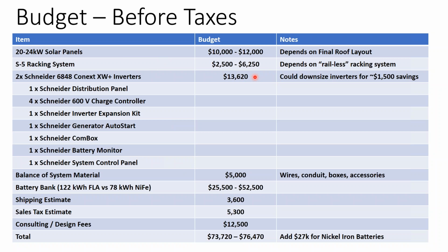In fact, it was more like 60 cents per watt. Now, normally a high-end inverter budget at the residential level wouldn't be more than 30 cents a watt, and on the low end, it might even be 15 cents a watt. And so we're spending a good 2 or 3 times as much on a battery inverter system, as far as the inverter budget goes, than we would on a batteryless system.